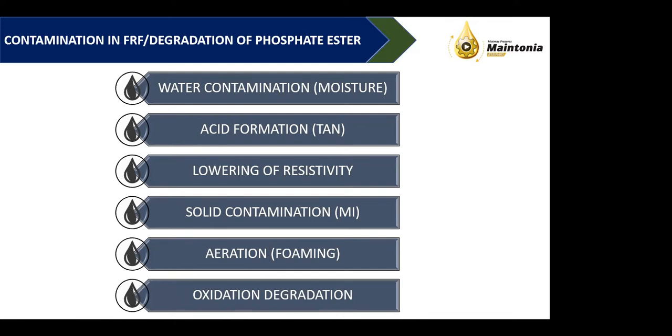Absolutely. And I would like to draw attention to a bump in front of your Ferrari. That is selection of the wrong filtration mechanism. What we saw and experienced recently was that one substandard machine added lots of solid contamination in the oil. The rubber hose was not compatible with the oil, so almost the entire hose was dissolved in the oil.